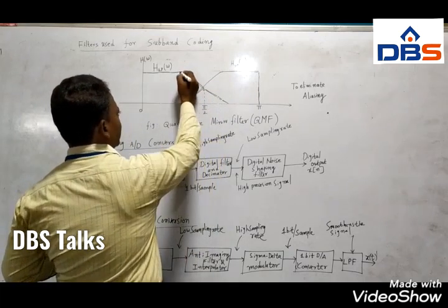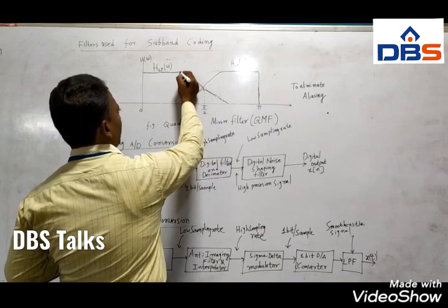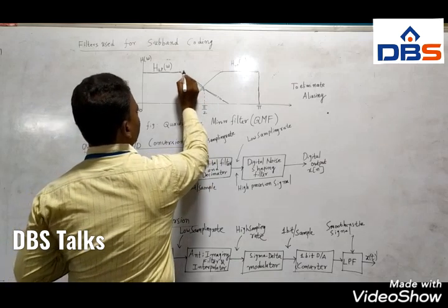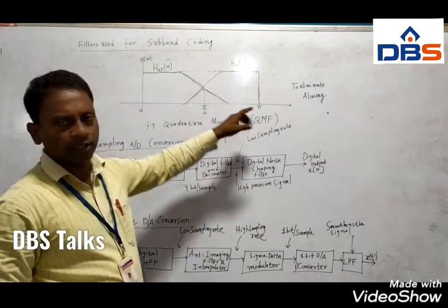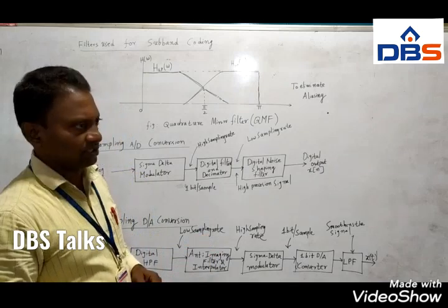And then what happens here, it is maximum, it is minimum. Slowly, suppose you have 1 here, it is 0, and 0.9, 0.1. Therefore you will get a constant characteristic from 0 to pi by 2. Such types of filters are used in subband coding of audio signals.